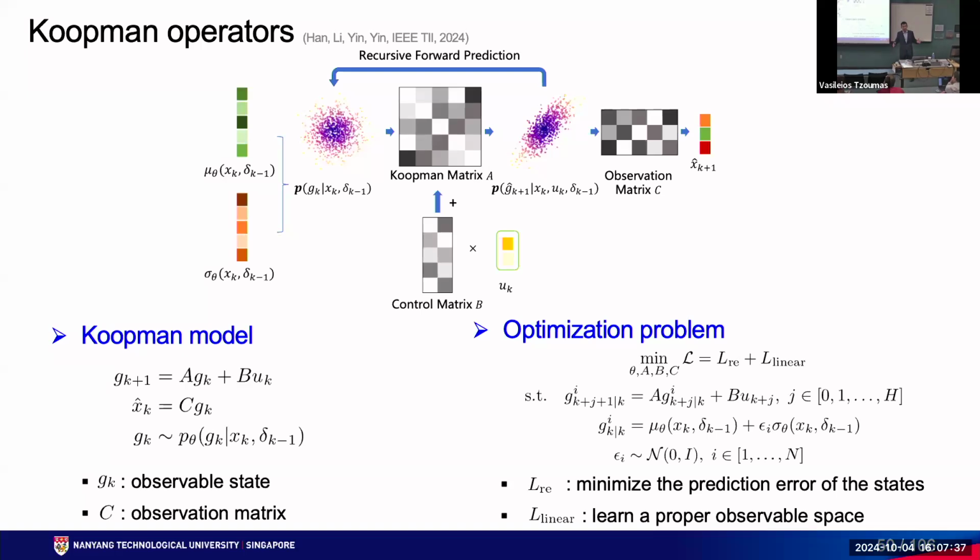So if n is 10, then our model should be able to provide fairly good prediction for the next 10 steps. For some applications, if the control or prediction horizon for MPC is chosen to be 20, then the model needs to predict the future states for the next 20 sampling periods. And this is the optimization formulated for Koopman modeling.